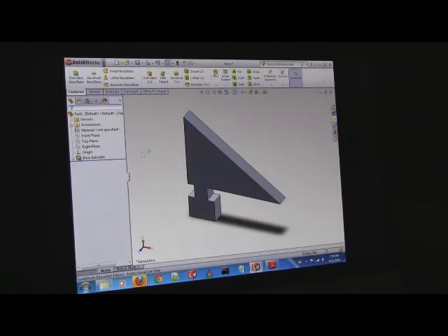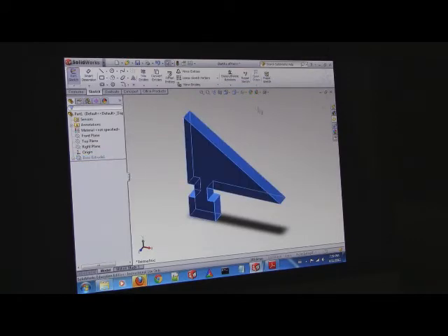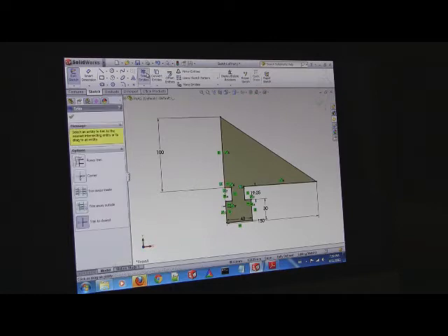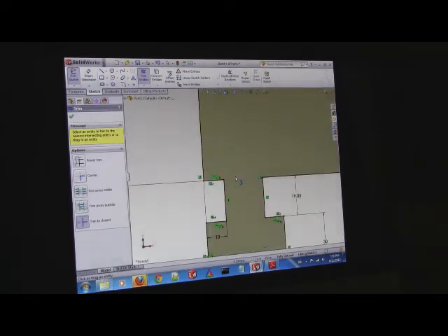What is the trim thing? Where did you find it? Let me show you. Okay, look at my screen right here. Trim, and then pick the bottom one, trim to closest. What does it do? It cuts. So select trim to closest, and now put it over this section right here, and see how it'll turn red for you. Click on that line, and that line will get deleted. It will trim the line.